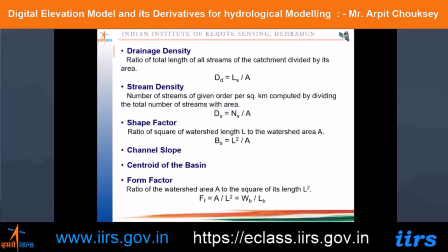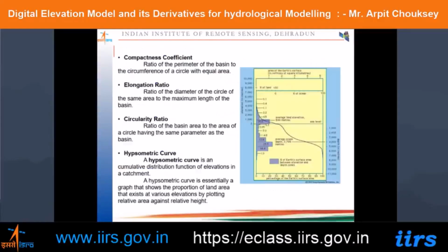Now I'll talk about some very brief applications of DEM, digital elevation model. Orthophoto production and topographic mapping. DEM is needed for ortho-rectification of an image, the process of removing the effects of sensor tilt and relief to obtain a photographic map with uniform scale.